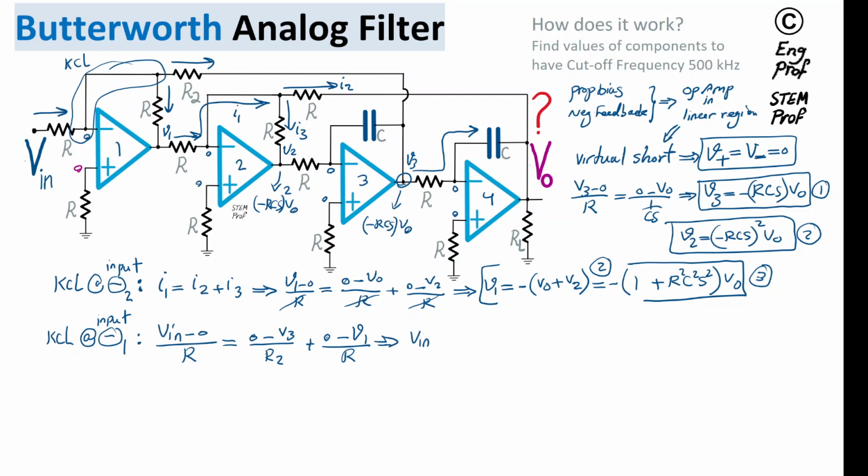Okay, so in this case, just reshuffling the values around, we would get Vin equal to minus V1 and plus R over R2 times V3. Now I can substitute equation 1. Equation 1 basically defines V3 as a function of Vout, so I'm going to substitute from that. At the same time, I'm going to substitute from equation 3 to write V1 as a function of Vout, and I'm going to use equation 1 to do the same thing for V3. So it's a combination of using equation 1 and equation 3 here.